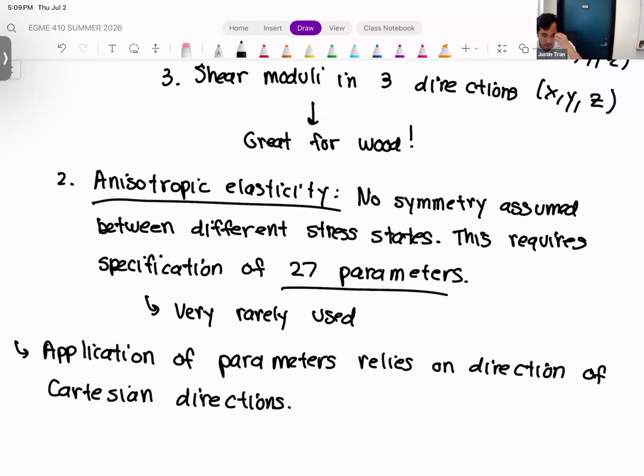Okay. And so in the most naive way, let's say that you're applying an orthotropic elastic material. You're applying a Young's modulus in the x direction, in the y direction, in the z direction. Now that makes sense mathematically, so for forming the equations, that's typically how we form them. But there are some practical difficulties that show up if you're applying this directly to a CAD.